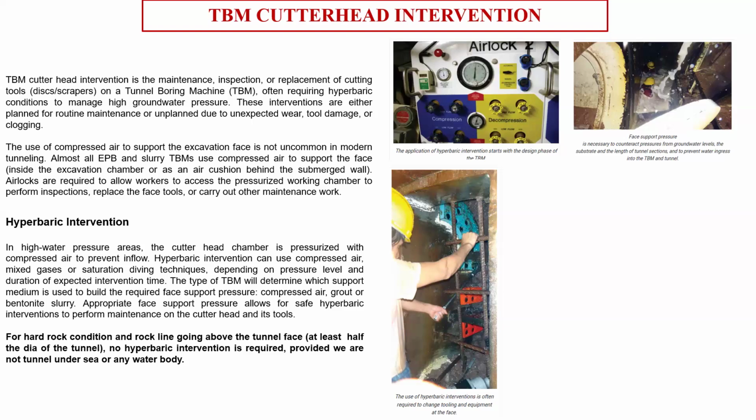It is flexible. If it is a curved alignment, it depends on how the alignment is moving. Accordingly, the articulation is being done. That is why nowadays the articulation system mostly follows the curve. Previously, there was a difference between the shield movement and the jack movement, so the shield and the jacks were not following the perfect curve.